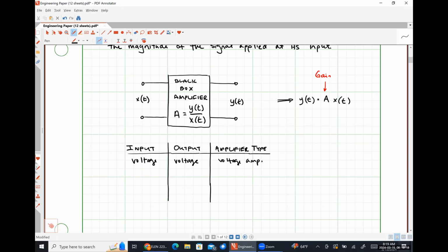But it's just taking a small signal from the output jack of your electric guitar, and that signal is very small because it's just based on electromagnetic induction, and then it's boosting it to a level so that when it goes through the power amplifier stage, which is a secondary stage, it's able to produce enough power to drive a speaker, like we talked about a little while ago, right? So voltage amplifiers are literally all over the place, and that's largely what we're going to focus on in this class.